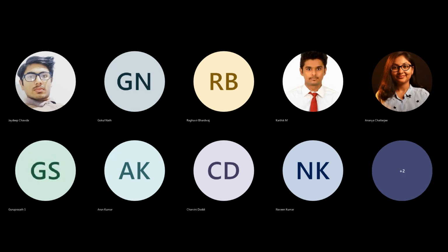Many analogies are there, like Reynolds analogy, which is the very basic analogy. Then Prandtl modified this analogy, then Chilton-Colburn analogy, von Karman analogy. One by one they have modified. Initially they assumed laminar flow, then they introduced turbulent, then viscous sublayers, then eddies. Finally they ended up with the Chilton-Colburn analogy. So if you have data for one transfer operation, you can predict another transfer operation provided many conditions are identical.